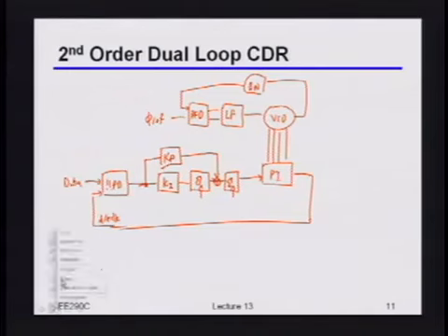So now indeed that bottom thing that we drew there, even though this is the CDR, and even though, by the way, almost all of this stuff is actually digital, what we're basically doing is building the equivalent of a phase lock loop. It's just that we know that the frequency range this phase lock loop needs to handle is probably way, way smaller than the frequency range we had to handle here, because here we're really just looking for a ppm offset between the reference crystal on our chip and the reference crystal on the other thing that we're talking to, okay?